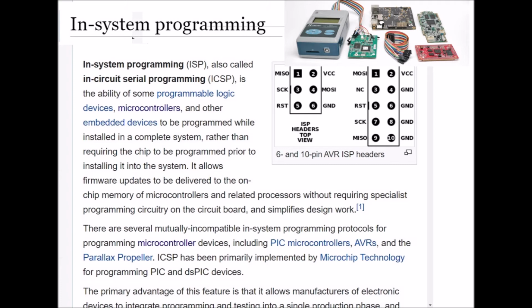Microcontrollers are typically soldered directly to a printed circuit board and usually do not have the circuitry or space for a large external programming cable to another computer. Typically, chips supporting ISP have internal circuitry to generate any necessary programming voltage from the system's normal supply voltage, and communicate with the programmer via a serial protocol. Most programmable logic devices use a variant of the JTAG protocol for ISP.